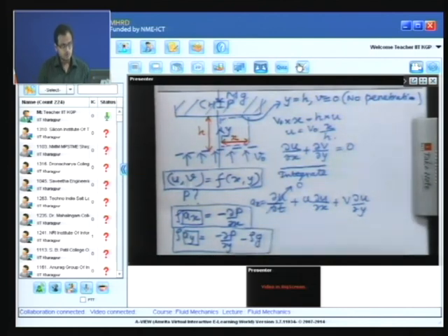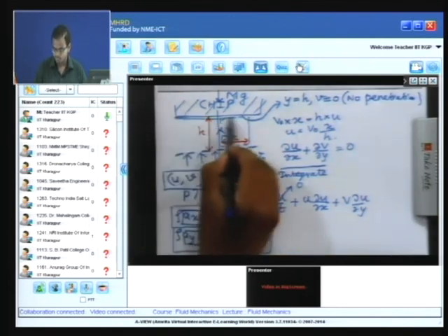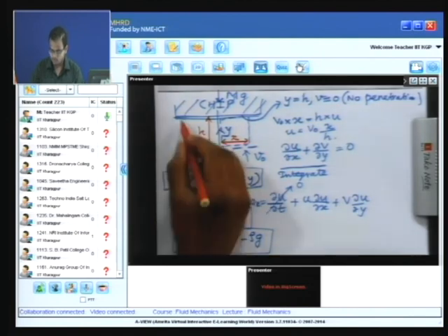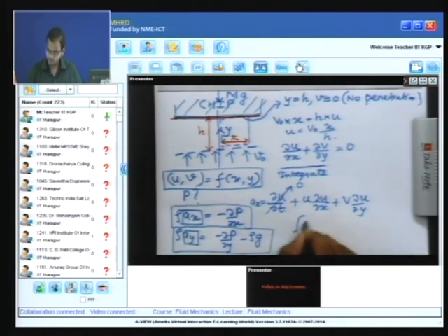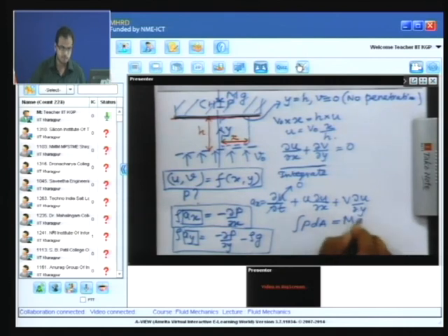Once the pressure field is found out, you need to integrate it over the area of the chip and then balance it by the weight. So, for the chip, the net force because of the pressure is equal to the mass of the chip times the gravity. So, by this methodology we can find out how much weight this blowing stream of air can support.